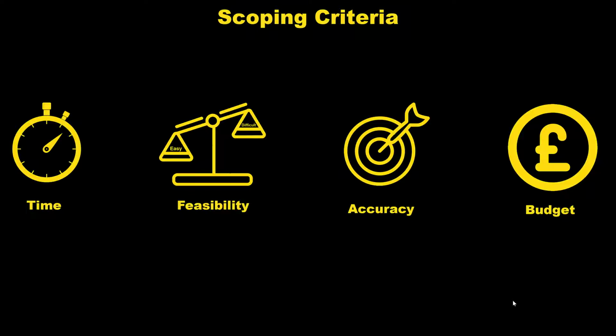So in that case, you'd use 3D scanning, as it's quicker and it's able to have a higher degree of accuracy and more suitable for such a big area, whereas physically measuring, it'll take you a lot longer and it won't be as accurate, yet it might cost more because it will take longer. So those are all factors to consider when choosing which route you want to go down when creating a digital environment when you don't have a CAD model.